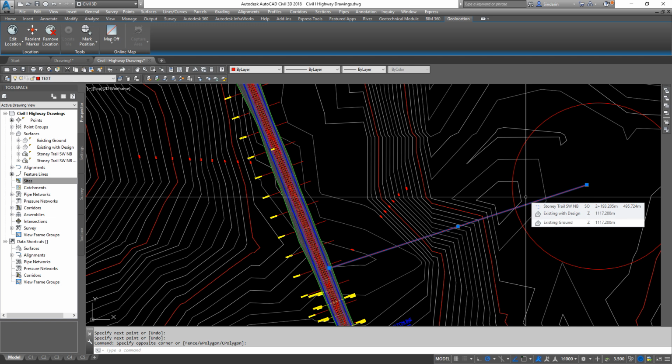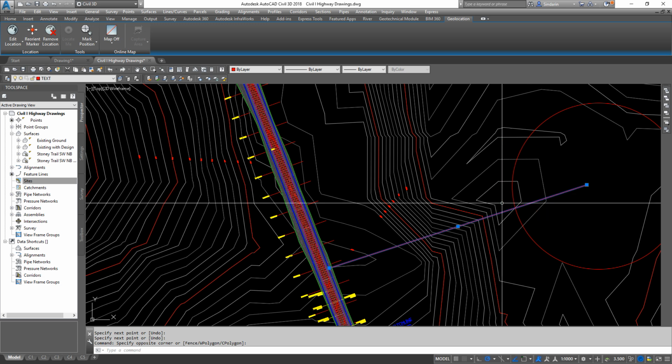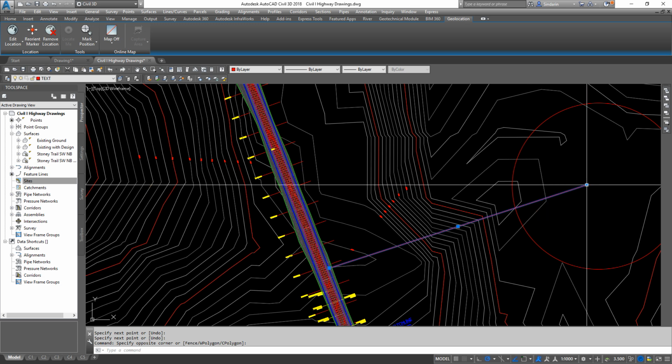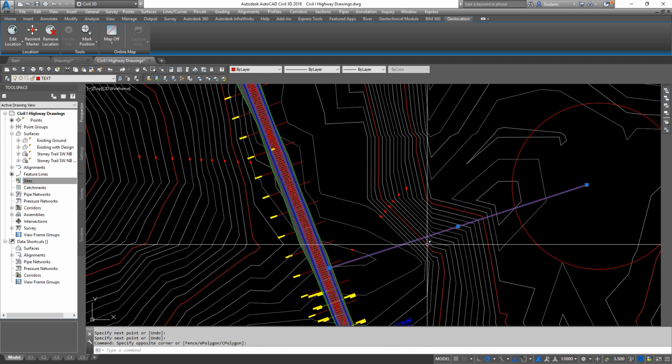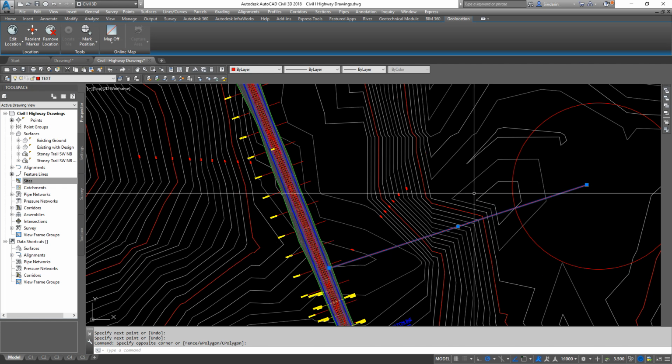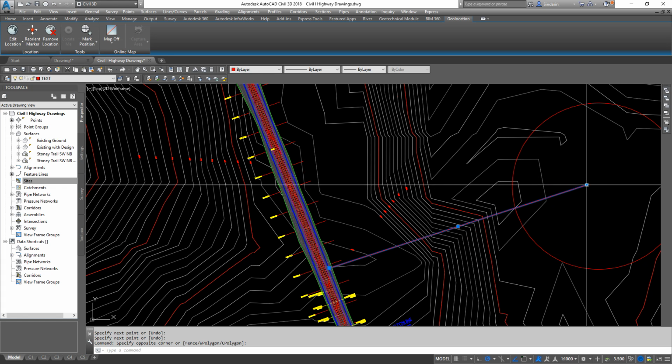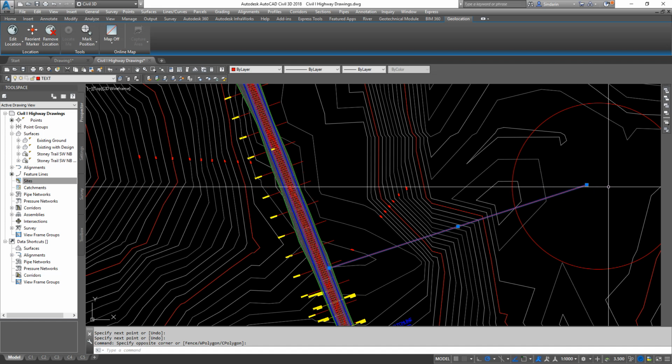Now that is how long an additional ditch would need to be in order to have water flow from the road to the pond. So we would need to figure out the elevation of the ditch over here. We'd have to run the calculations at 620 meters long at 0.5%, maybe 1%, to figure out the elevation over here.